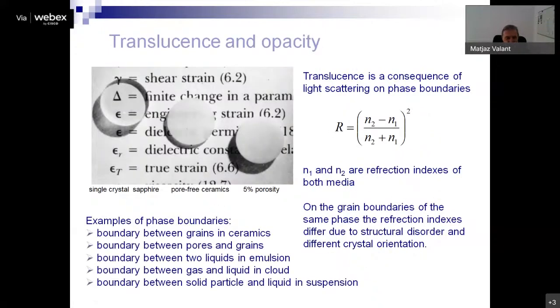Now, we talked about sapphire, that is transparent, but corundum, which is also alumina, is white. It's rarely even translucent. So why so? The reason is that a single crystal has no or very, very little defects, line defects, or more extensive defects on which the light would scatter.